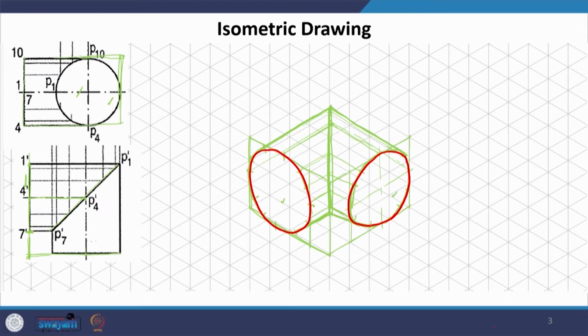So, it appeared very simple because we had the reference planes properly taken. We know this reference plane, this was the reference plane. I am just marking the endpoints of the reference planes for squares here. Once we put them together, it was very easy for us to arrive at the intersection of the circle in isometric projection, and it will be the line. We can draw these thin lines, we can retain them, but this is exactly what we are going to be seeing if two cylinders of exactly the same size, same radius, intersect like this, perpendicular. Okay.